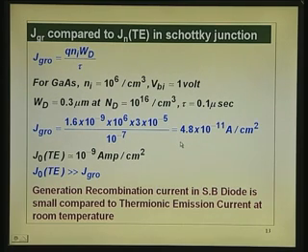So, actually you may not have to worry at around 0 bias, but when you go on increasing the depletion layer width, what would happen? In the reverse bias condition, this quantity keeps on increasing, the width of the depletion layer. Supposing the width of the depletion layer goes up from 0.3 micron to 3 micron, 10 times more. This can become 10 times more. That is 4.8 into 10 to the power minus 10. Still, it is not bad. It will not affect so much. That is what we are telling. Okay. Forward bias.